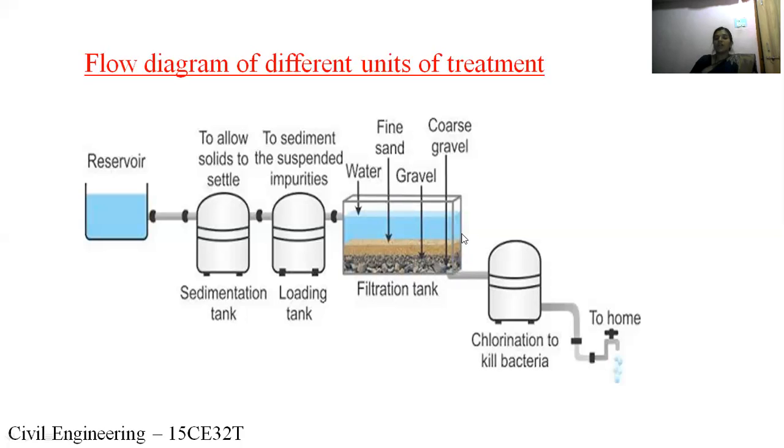Here in the filtration tank, a layer of coarse gravel, then gravel, then fine sand. So this filter media is provided for the filtration of water, and above that water is made to flow here, and water is made to stand here, and the water will percolate through this filter media, and the clear water will be taken to the next treatment unit.